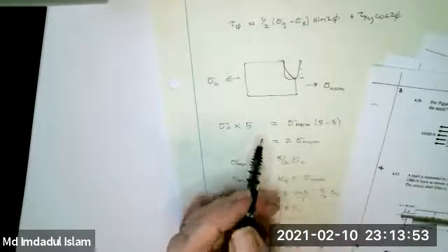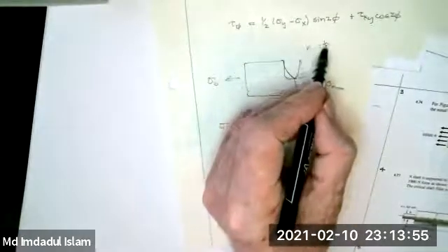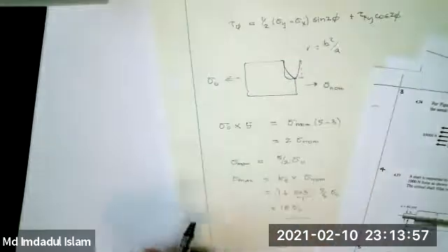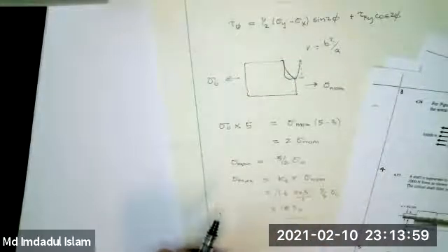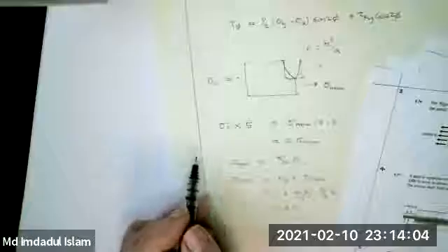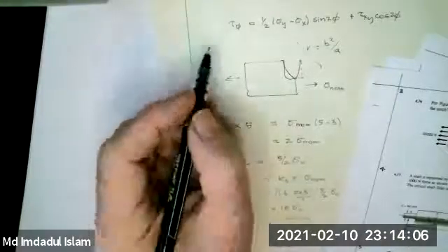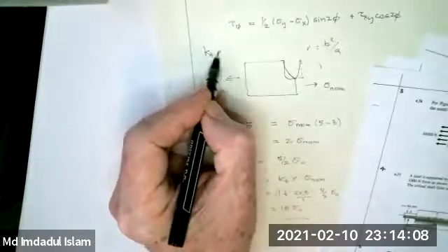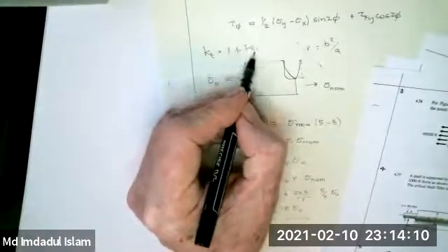Okay. So we couldn't use the formula 1 plus 2 square root of A over R? You could, and you'd have to go get what R is. Okay. And R is B squared upon A. So you'd just be doing the extra calculation. You'll get the same answer. Okay. Thank you. When you're calculating elliptical stress concentration factors, if you're given A upon B, the easiest formula to use is 1 plus 2A upon B.